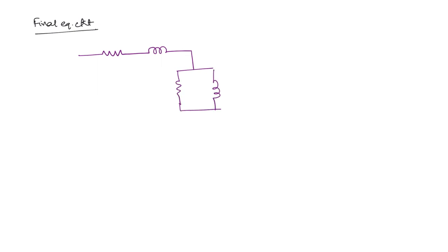So now we can combine both the stator and rotor circuits to get the actual final equivalent circuit. This will be just like a transformer, with only slight differences in the parameters. These are the core components: R1, jX1, RC and jXM. Instead of the subscript 1, you can also use S, where S means stator side.